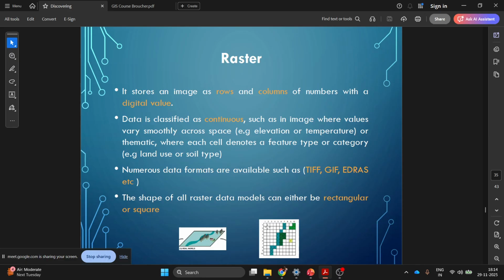And here you can see all the white boxes, white squares, represent the ocean or other places, and the blue boxes represent the river, and the trees that are there are also represented in this raster file as boxes. And the house is also represented as a small square area. So that is how when you convert vector data into raster data, you can see some errors happening. In order to decrease this error, I can reduce the grid size.